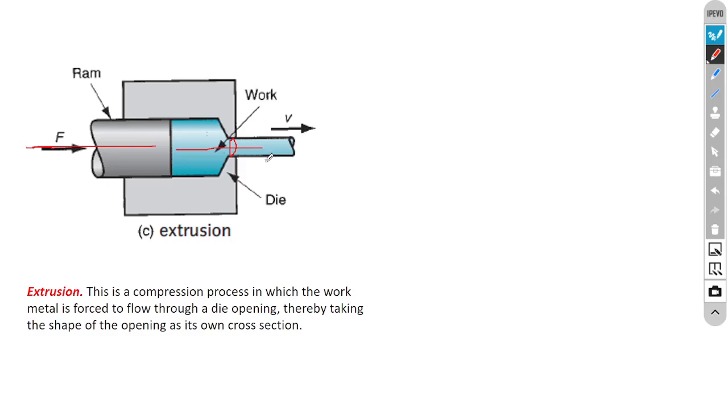Swell ratio is very small since the material is not liquid, not plastic, but a strong material. Swell ratio is almost 1. Not 1, sorry, almost 1. So the size of the product is almost equal to the size of the orifice or the die. In extrusion, the material is pushed, compressed, and forced to flow across the orifice.